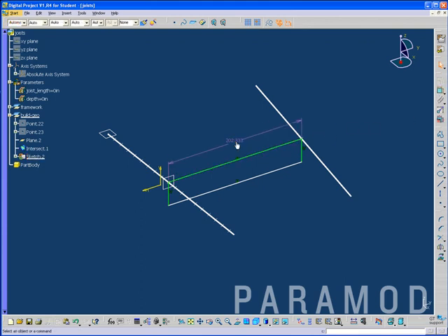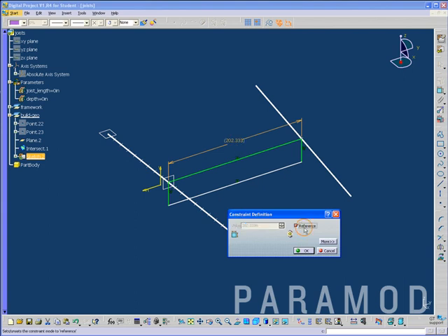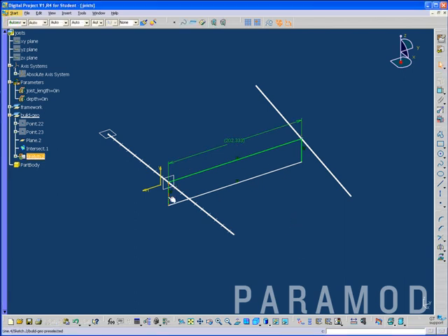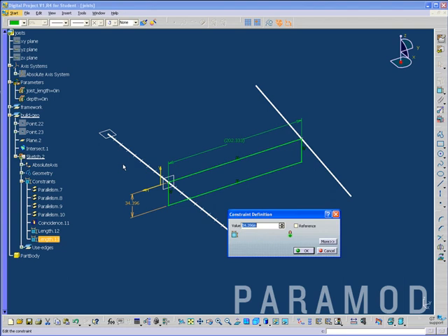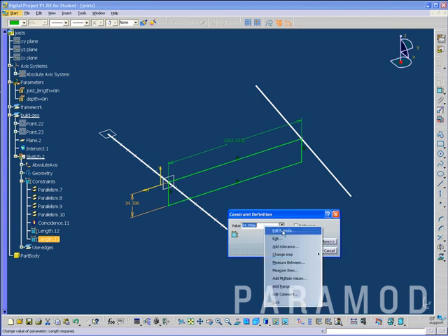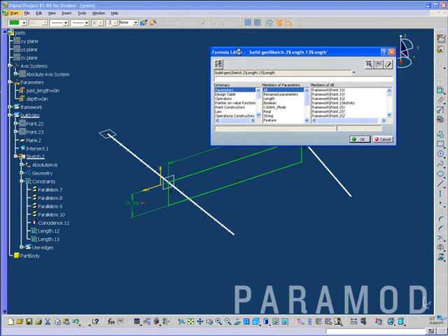And so our top line is green because that's just driven between those 2 lines. I want to add a reference geometry to this. So I'll just double click and say reference. And I want to set the depth of this. And so right now we'll expand the sketch, find our constraints. We want to set joist length equal to 12. And then we're going to set this length. We'll edit formula. We're going to set this equal to the depth.